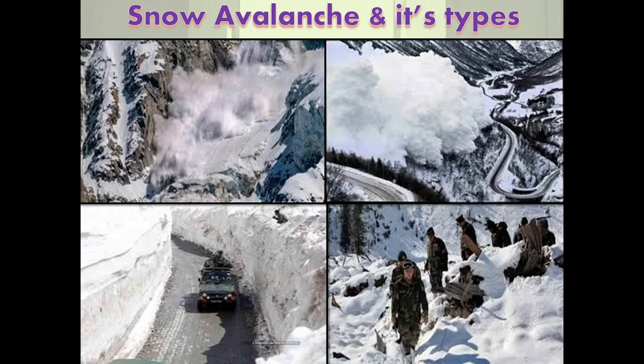Loose snow avalanches form from snow masses with little interconnection among the individual snow crystals. When such snow lies in a state of unstable equilibrium on a slope at its natural angle of repose, a slight disturbance sets progressively more and more snow in downhill motion. If enough momentum is generated, the sliding snow may run out onto level ground or even span an opposite valley slope. Such an avalanche originates at a point and grows wider as it sweeps up more snow in its descent.